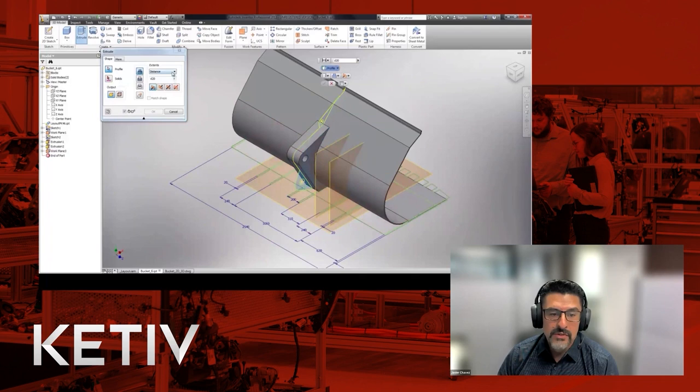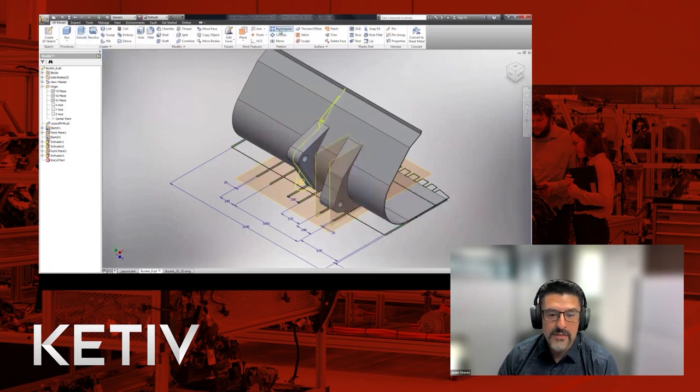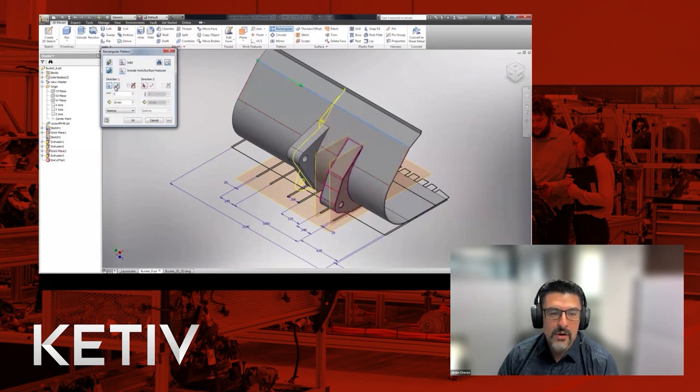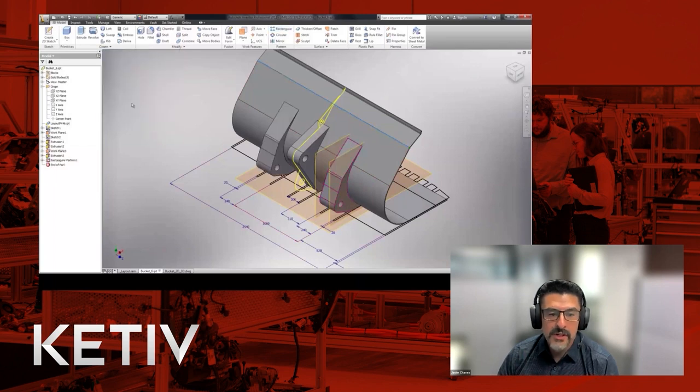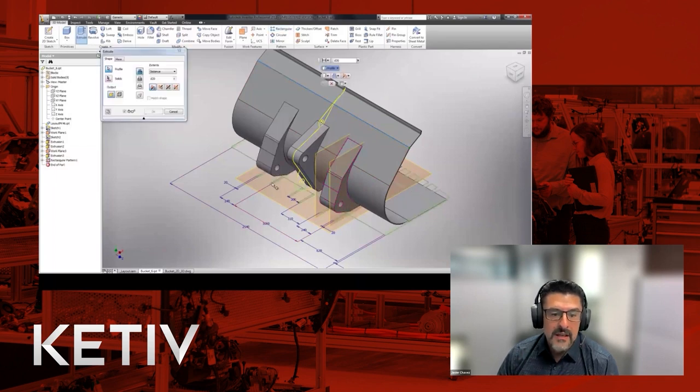And once you do reference them, that's how you control them, right? So we're going to extrude from plane to plane to create more gussets here. And you'll notice that they're fairly chunky and big. We'll refine those as we go. But in each of these new pieces of geometry, we're creating new bodies, and we're working in a part environment. So it's important to note that this is one part, even though technically it could be an assembly. And if it's static, this is the best way to handle it.